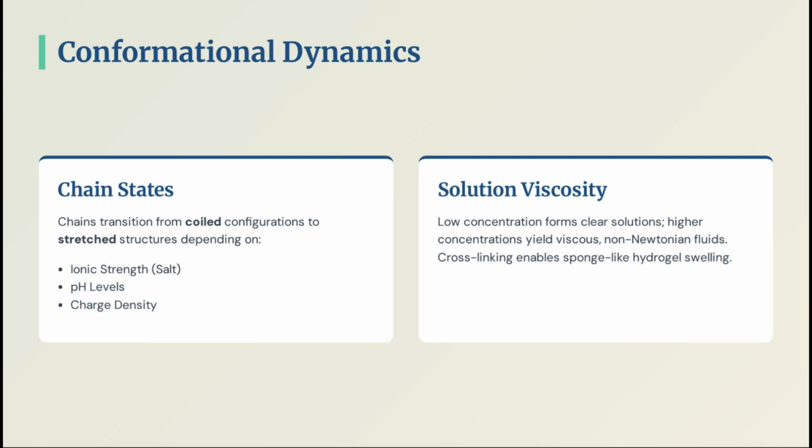Cross-linking reactions turn these linear chains into three-dimensional, hydrogel structures akin to high-capacity sponges that hold massive amounts of water. Commercial product series are categorized by their molecular weight, intrinsic viscosity, and charge density or degree of molar substitution. Today, this versatile agent is heavily utilized in wastewater treatment, oil and gas production, papermaking, mineral processing, textile finishing, and agricultural soil management. With these foundational principles established, we will now explore its practical mechanisms in water purification.